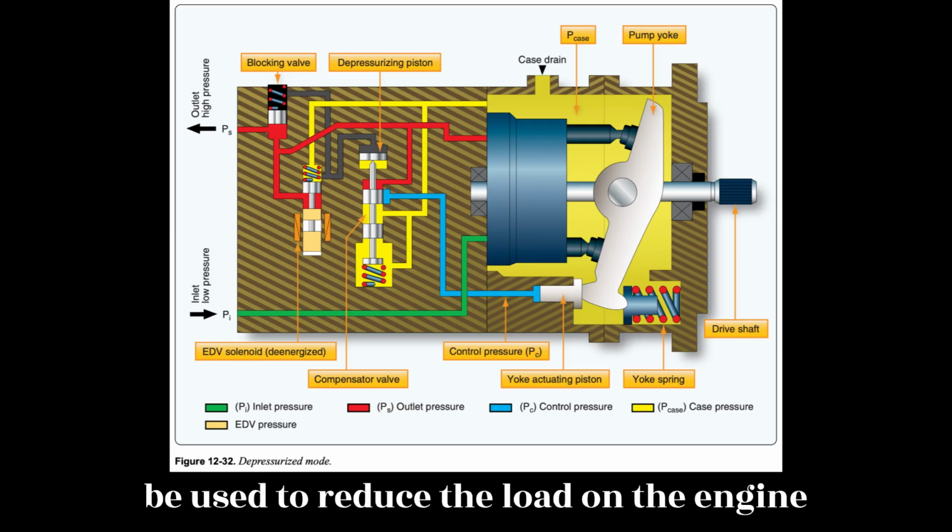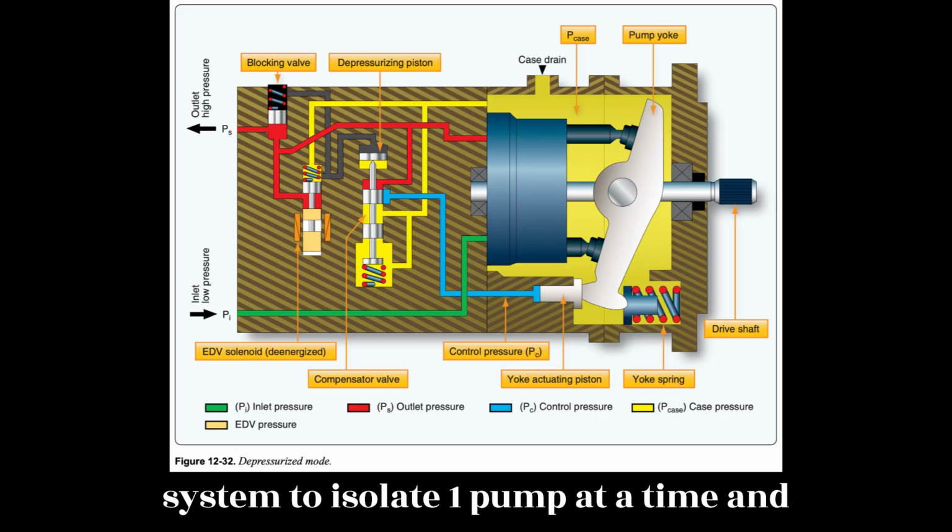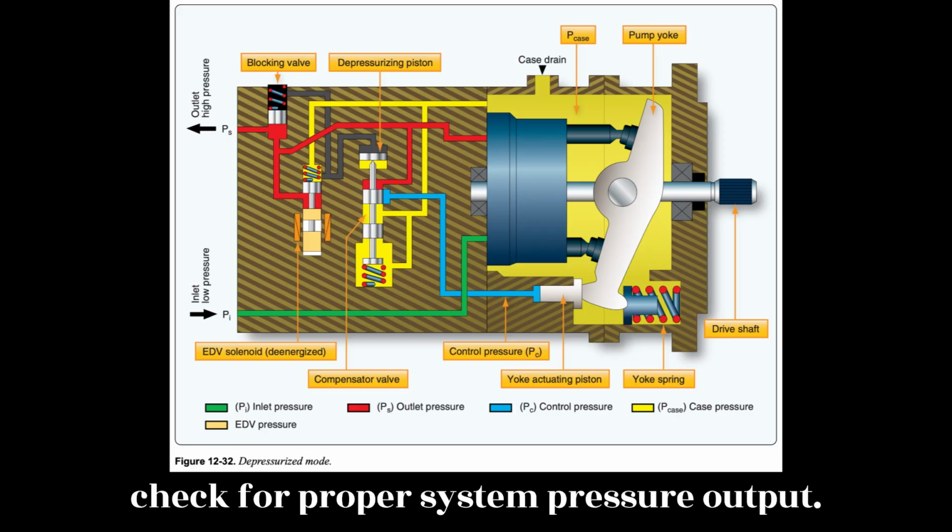This depressurization and blocking feature can be used to reduce the load on the engine during startup and, in a multiple pump system, to isolate one pump at a time and check for proper system pressure output.